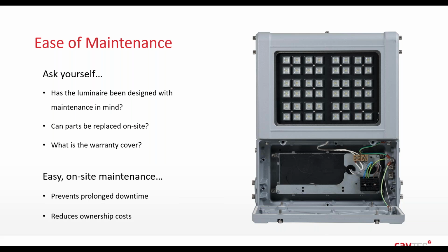And lastly, you need to check the terms and conditions of the warranty cover, not just the duration of the warranty, but also what components are covered and what processes must be followed if the unit or component becomes defective. So find a luminaire which answers these 3 questions positively, and you'll have a fitting which is easy to maintain and allows the maintenance to be carried out on site.